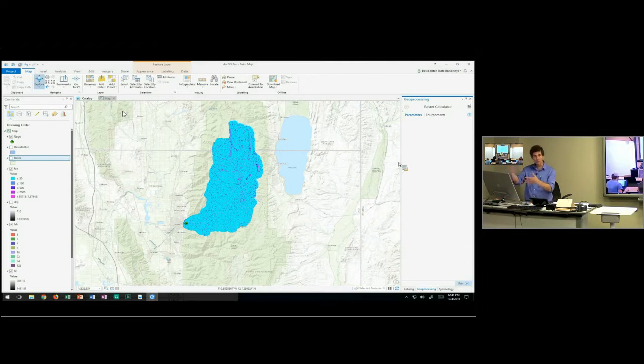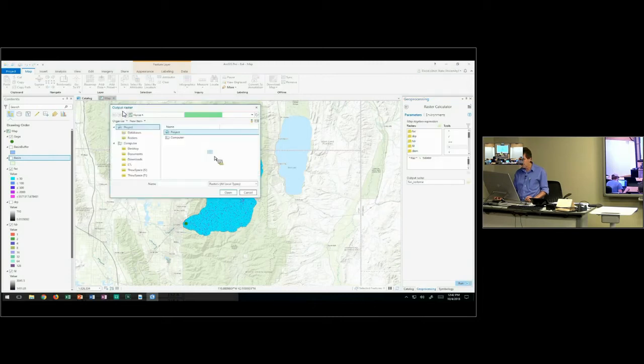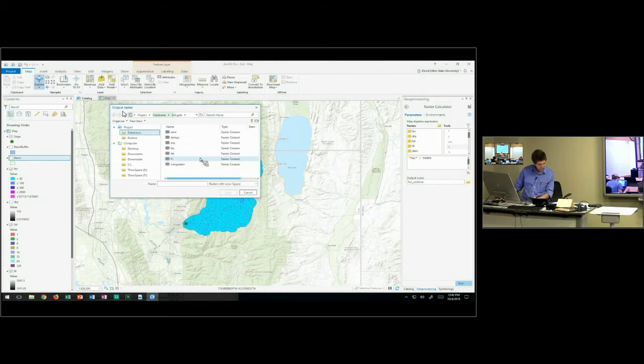This is where all the choices of stream drops and the stuff we spoke about last time come into the choice. I'm just going to go with 50,000 because I know that works reasonably well here by trial and error, and I'm going to put this in my geodatabase and call it STR for streams.